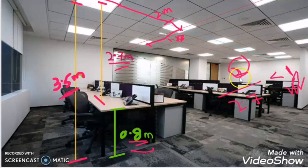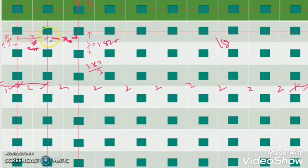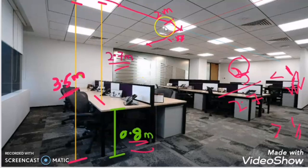Suppose the distance between the lights is 3 meter and the clearance height is 2.7 meter, then the ratio will be greater than 1. In that case, our light distribution is not correct and the number of lights we calculated is not correct. So we always have to check that this ratio is less than 1. We satisfied the two conditions: the lights are distributed evenly, and the ratio of the distance between the two lights and the clearance height is less than 1.